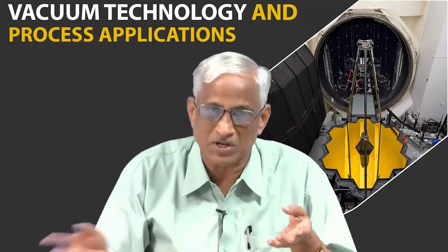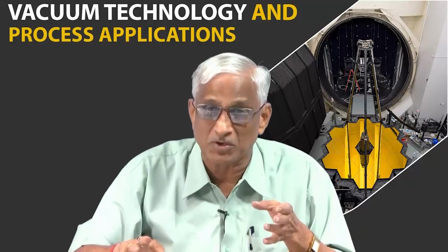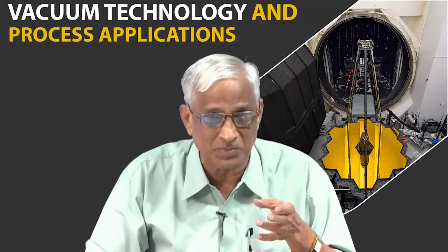If it is a diffusion pump, continuous backing. If it is a turbomolecular pump, continuous backing with a dry pump. And if it is a cryo pump, only initial vacuum, but there will not be a backing vacuum pump. You have to close that also. And the main isolation valve should be carefully opened.